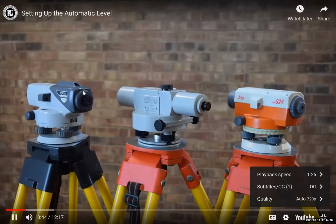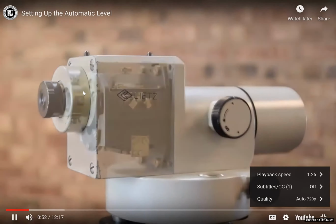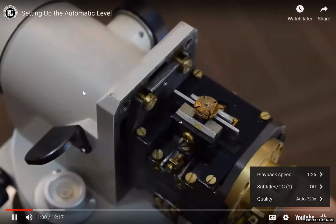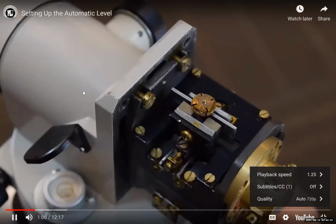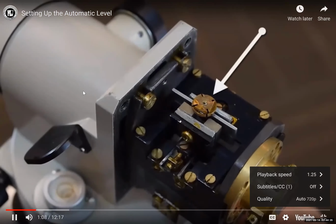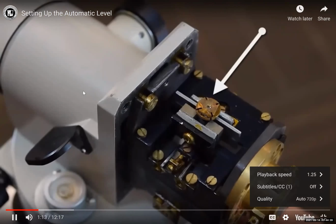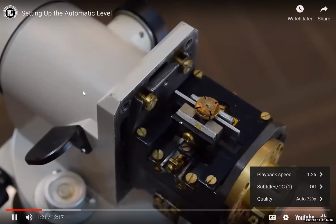What makes these levels automatic? Well, each one contains a tiny set of mirrors that move automatically in response to Earth gravity, ensuring that the instrument line of sight is always perfectly level. If the instrument settles during use, this automatic compensator adjusts the line of sight simultaneously. Here you can see the top of the mechanism moving as the instrument is tilted. Because they contain compensators, automatic levels give greater precision than older uncompensated instruments can.